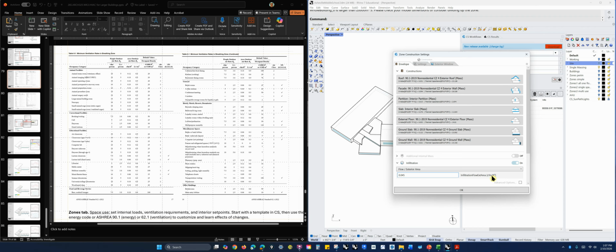I'm just saying that obviously, so let's go back. How our envelope is arrayed, like how much insulation we have and if there are any breaks in the insulation, will have a big effect on how much heat we gain or lose, on the energy performance of the building.